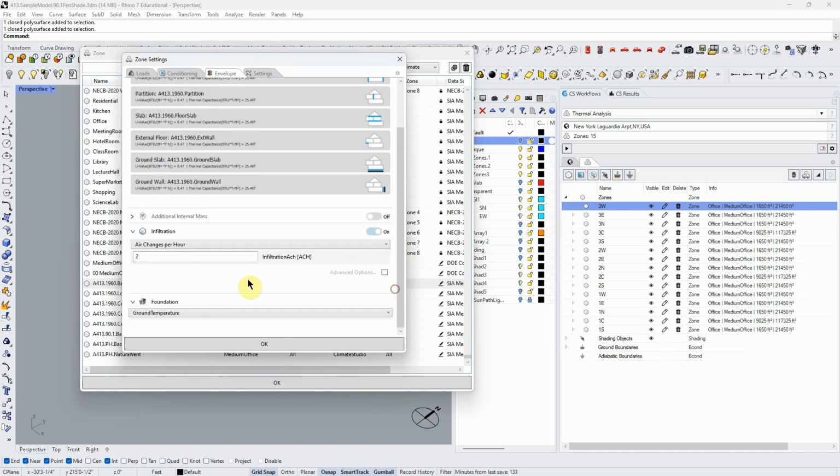Air infiltration is huge. If you think about it, whatever you do in terms of trying to control heat flow, if you have a bunch of leaks in your envelope, that's going to completely undercut it, right? So the more airtight you can make the building, the better, but it costs money to do that. In old buildings like the Guggenheim, the volume of concrete is very airtight, so that's good. But I'm sure they weren't considering it around the windows, and so it's probably a very leaky building. So this is a big parameter that we need to know about. In larger buildings, it has a huge effect.